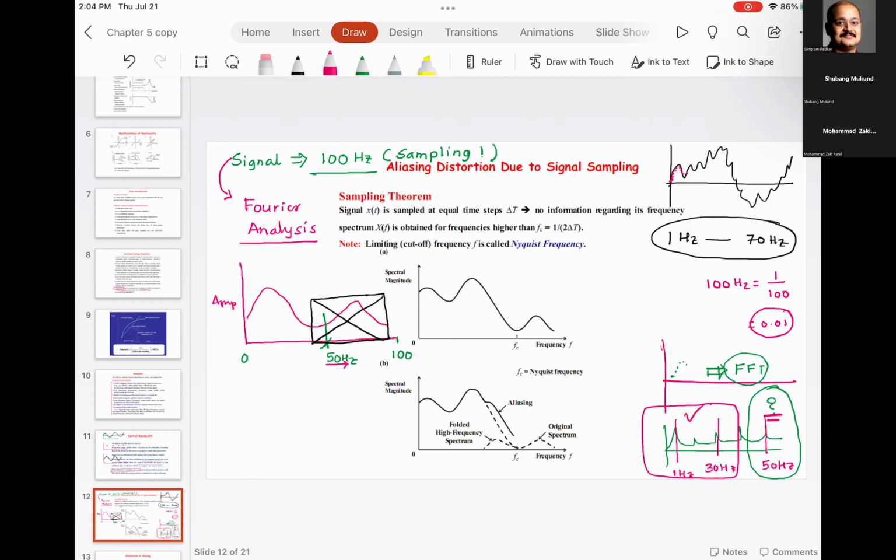But then what started happening was that we started to vibrate the shaker. We tried to do a sine sweep. We tried to vibrate the shaker at 60 Hertz, 70 Hertz, but the accelerometer we used to capture the data was capturing data at 100 Hertz. So the frequency spectrum that we got for the diagnosis of that shaker was incorrect, which means from the frequency spectrum, we say, hey, we have this huge peak at 80 Hertz, or we have this huge peak at 40 Hertz. But you know what?